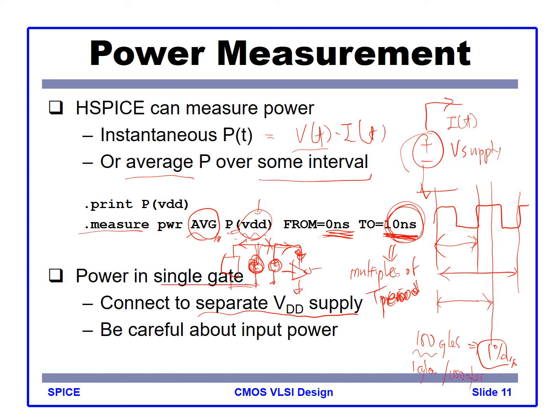But you also have to care about the fact that the gate has some finite input capacitance. The other driving cell needs to drive this input capacitance, and that means the power to drive this gate is also drained from the other supply network, the supply voltage source.